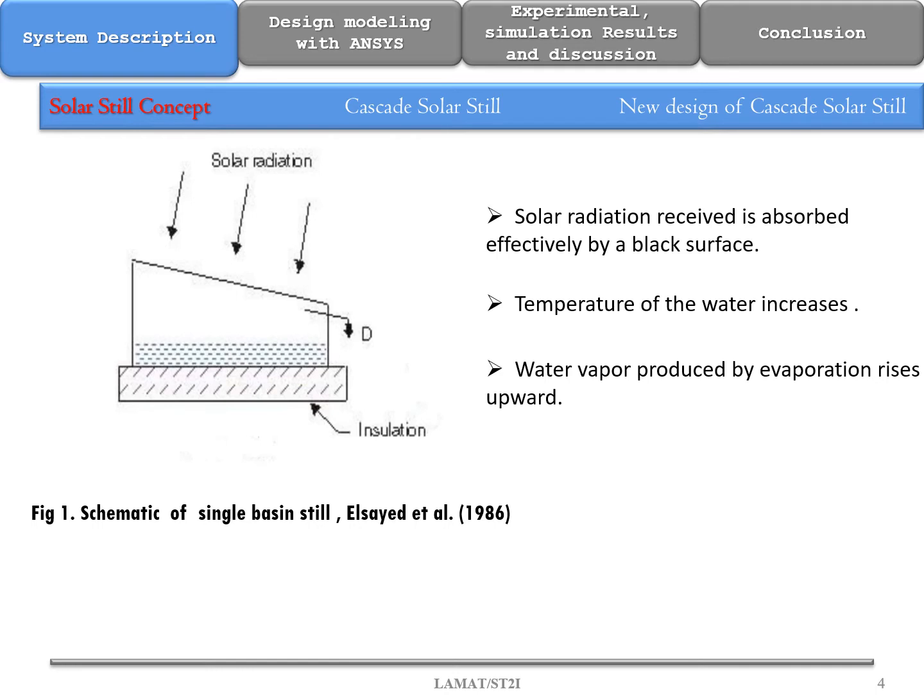So the solar still is a very simple device and cheaper than other forms of desalination. However, in comparison with the other techniques, the yield of a single basin solar still is very low. The investigation indicated that the depth of water in the solar still inversely affects the productivity of the still. So reducing the brine depth in the still improves the productivity.